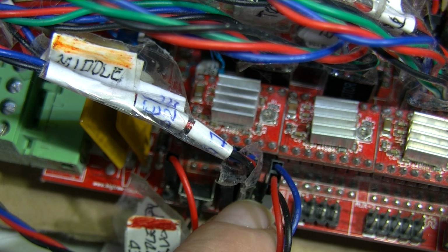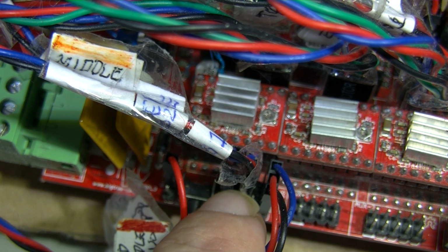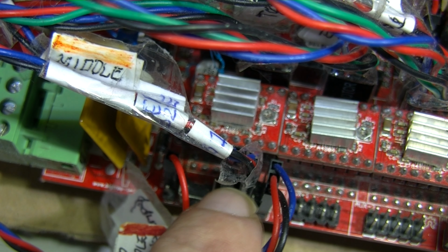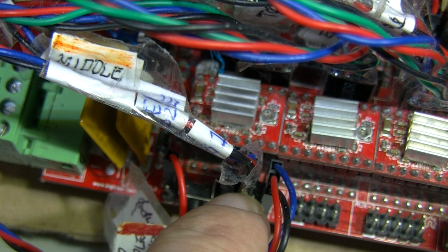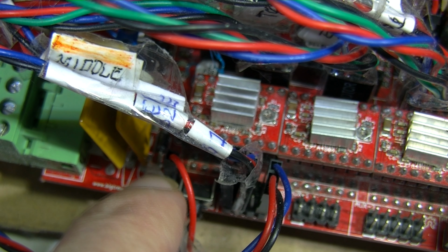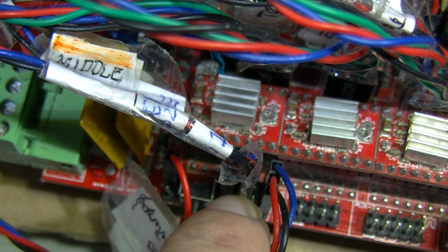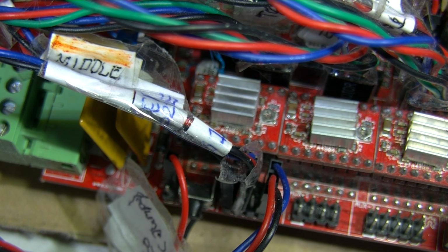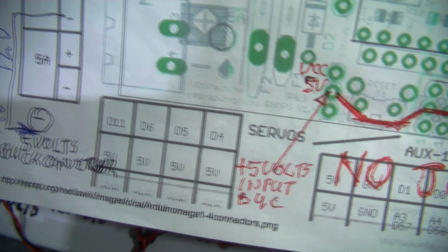Okay. Now in my case I do have a servo port 3, 1. So what I intend to do is plug this into the 5 volts of the servo port, because they're all 5 volts down the middle track of the servo ports. Sorry if I'm pointing to the wrong place here, yeah. And then plug that into pin 44. Let me show you this printout map. Just zoom out a bit so you can see.